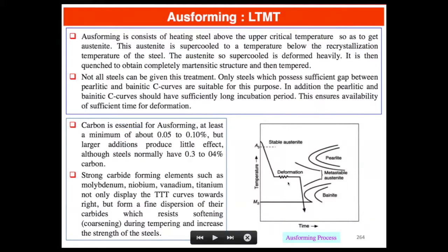But it's supercooled austenite. This is very heavily deformed. It's not going to recrystallize. We're not hot enough for that. We don't have significant grain growth going on.